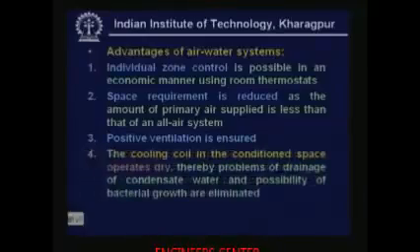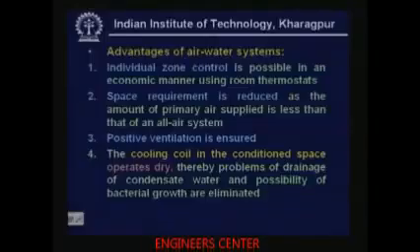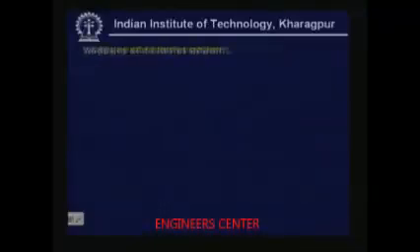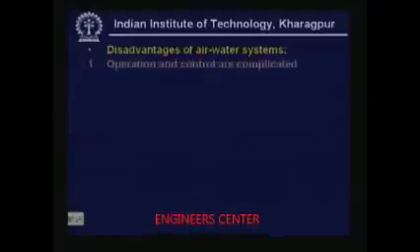And the cooling coil in the conditioned space operates dry, so the problems of drainage of condensate water and the possibility of bacterial growth are eliminated. Okay, so these are the main advantages of air water systems. Now what are the disadvantages of air water systems?